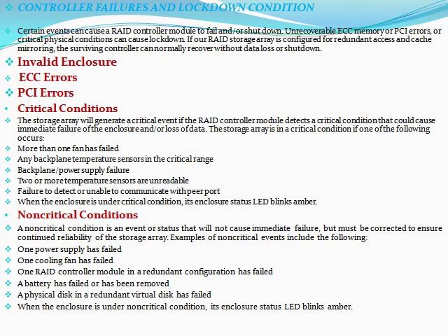The enclosure status LED is... The RAID controller firmware detects an ECC error and can recover from a single-bit ECC error whether the RAID controller module is in a redundant or non-redundant configuration. A storage array with redundant controllers can recover from a multi-bit ECC error as well, as the other RAID controller module takes it over. Now, PCI error.